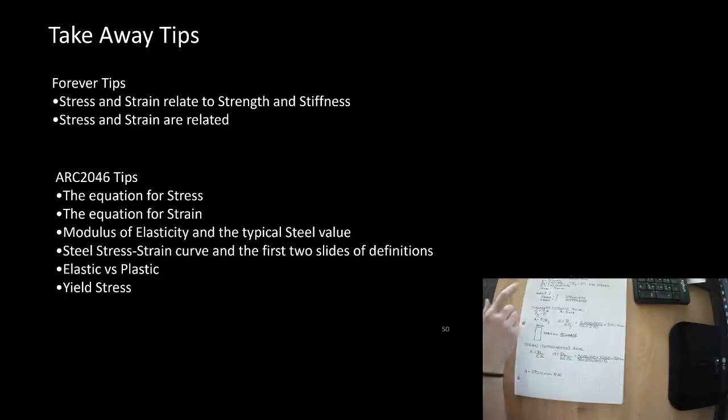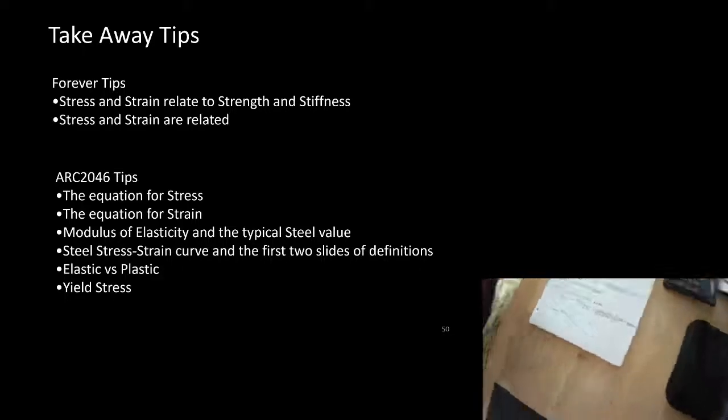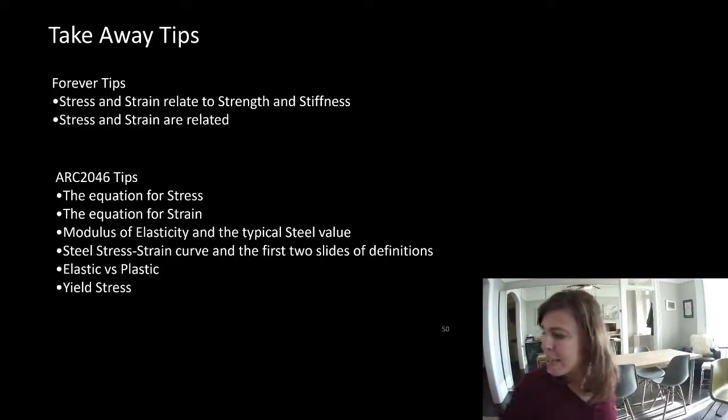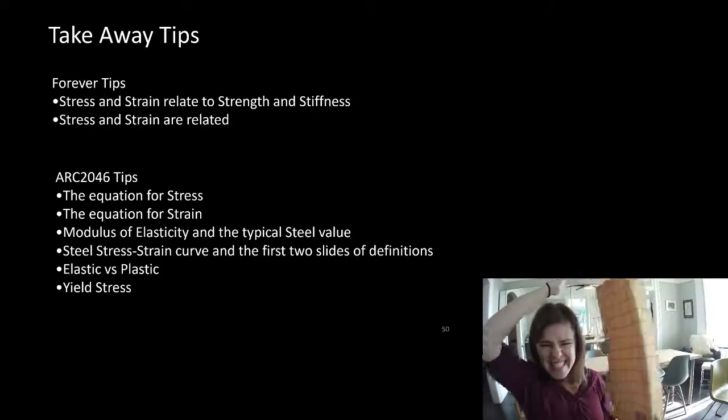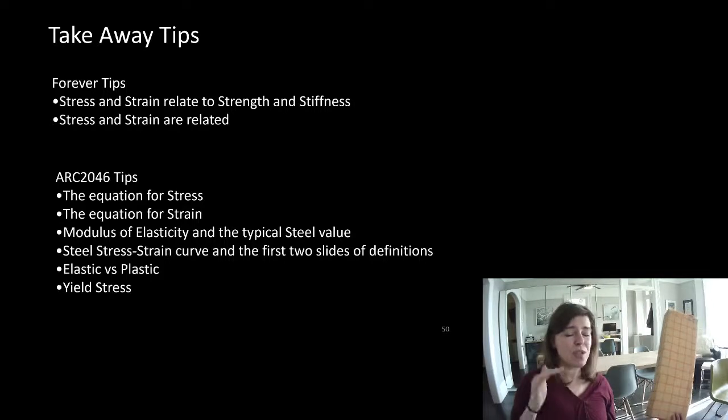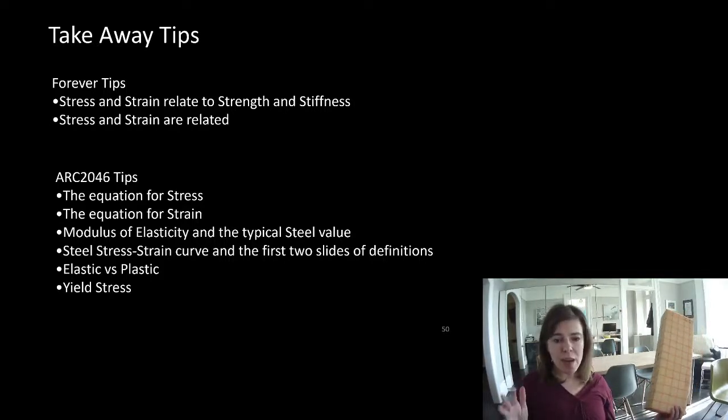Now, this was already factored for us, and we know that we wouldn't have actually used the factored load in the deformation calculation. And we didn't actually apply our reduction factor. They gave us a reduced stress. So we know there are still some things we don't understand. And even more, there's that pesky thing that I have told you about before called buckling. And this didn't even think about buckling at all. So it seems like there's still more we need to learn. But generally, the basic premise of it for capacity, we now have. We've got it.